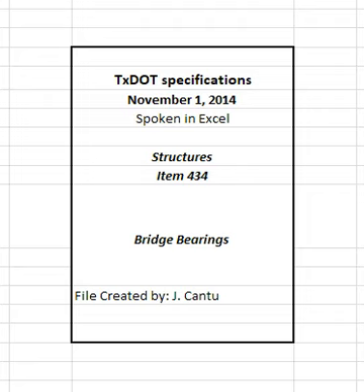3.3 HLMR Bearings. Electronically submit shop drawings for the complete assembly, before fabrication of HLMR bearings, in accordance with the plans. Provide a bearing layout with the shop drawings including geometric placement on substructure. Provide design calculations sealed by a licensed professional engineer.